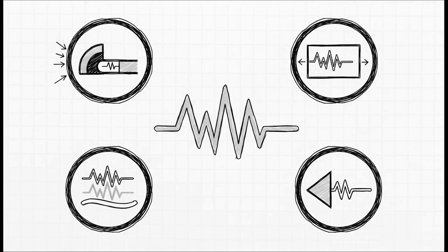Now, beyond aliasing, the big fight in the digital world is against noise. And the good news is, you've got a whole toolkit at your disposal. Things like proper shielding on your cables act like armor against outside interference. You can use filters to chop out specific frequencies you don't care about. Signal averaging, where you take tons of measurements and average them together, is great for smoothing out random noise. And using differential inputs is a really clever trick where your amplifier can automatically subtract out any noise that's hitting both of your signal wires.